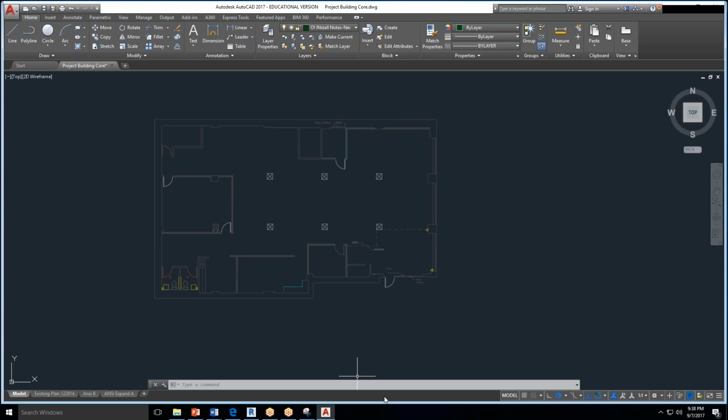Okay. But if it placed it already, Karen, you can click on it, and when you click on the roof, it should say in the properties side menu the height of it, and if it says level 1, there's a little drop down menu, and you just change it to level 2, and that should correct it.